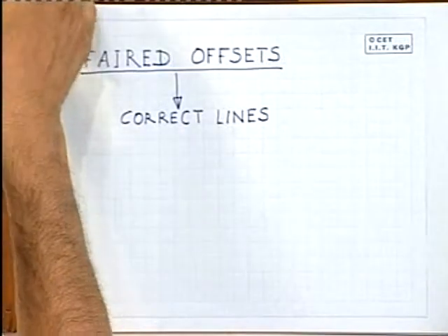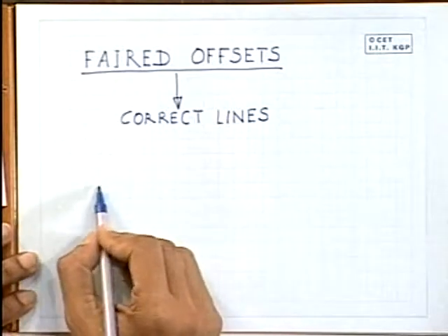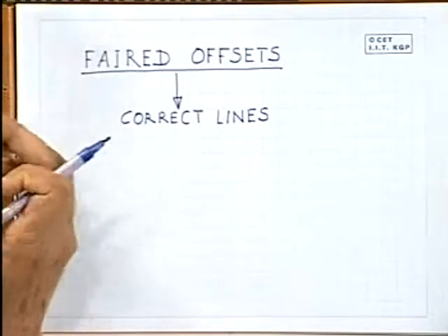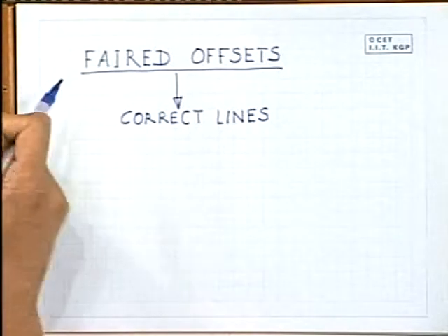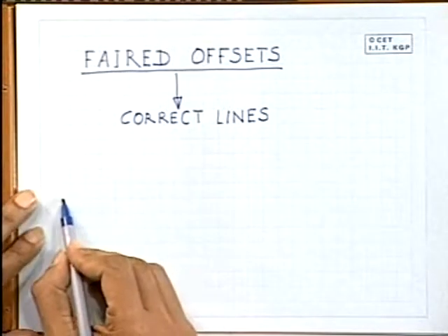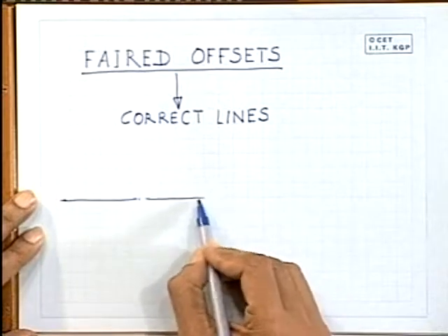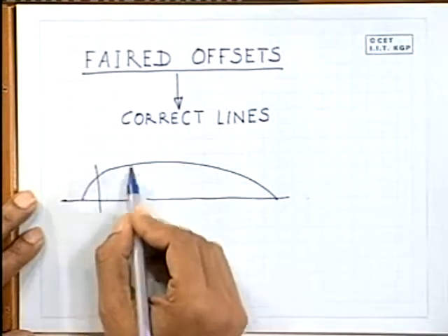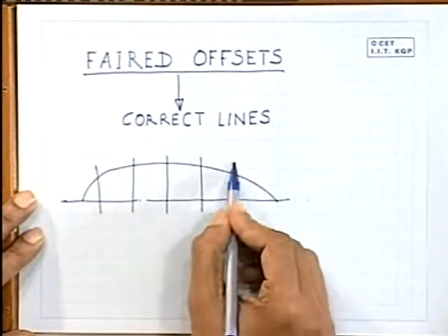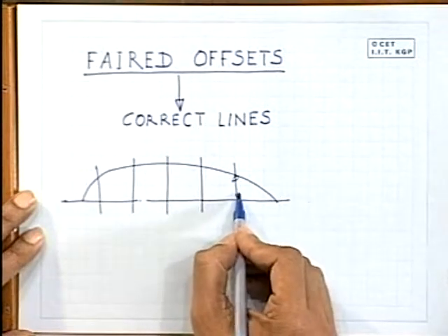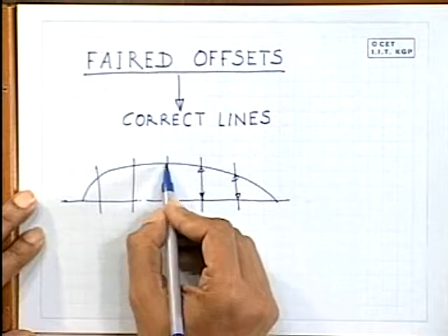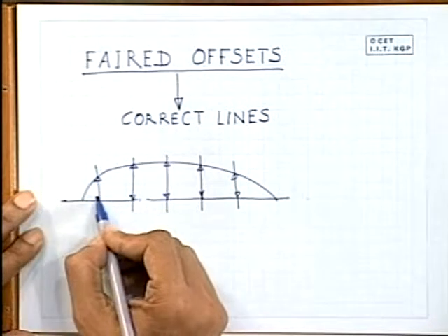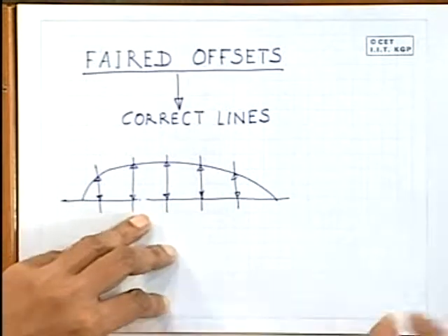And before that, the offsets are nothing but your half breadths. Say you draw a particular water line and you take the half breadths at the stations. So this is the offset. Now these are the molded half breadths, so these are called offsets. And these offsets are depicted in tabular form, that is called an offset table.